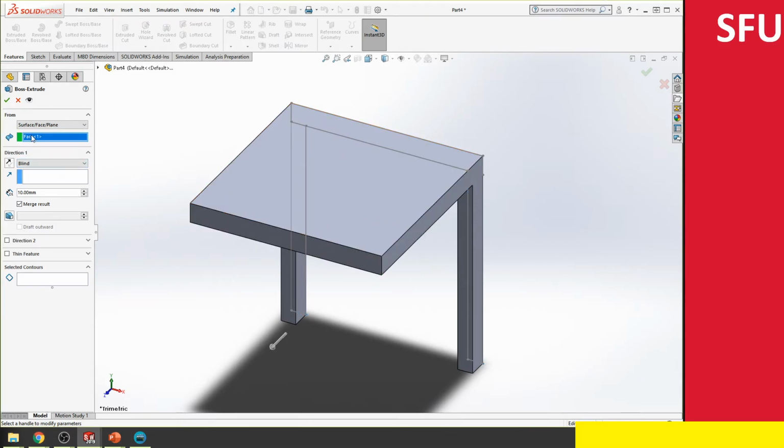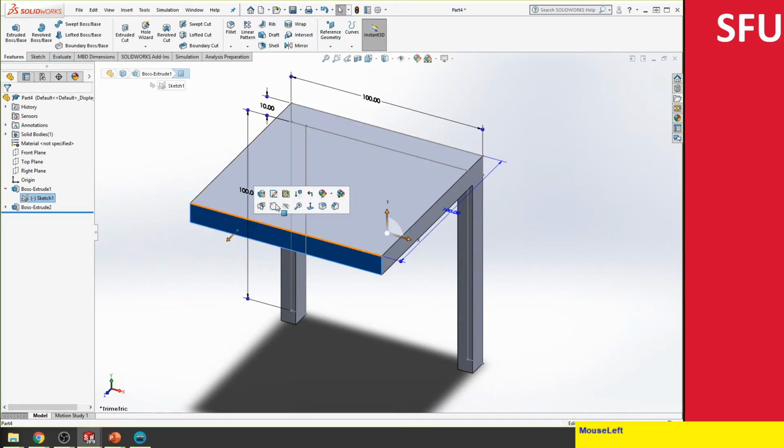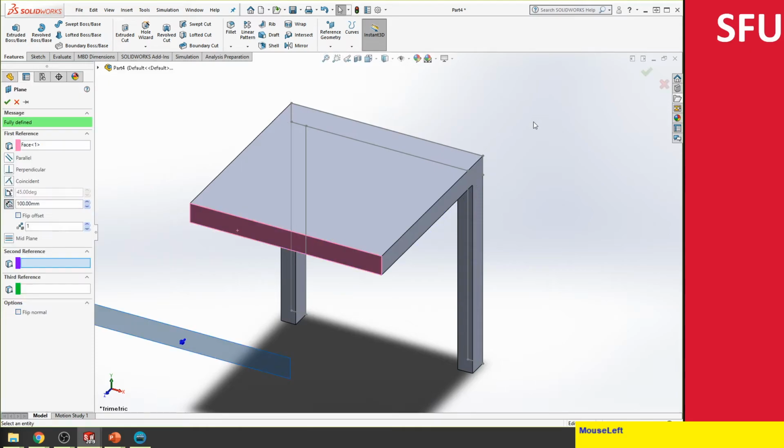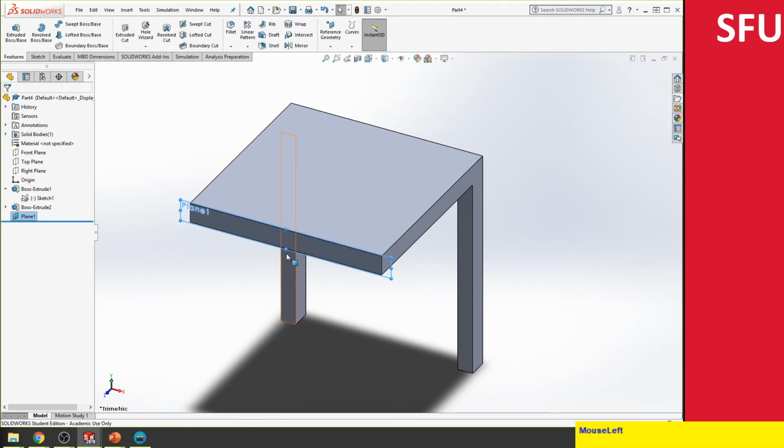If you really wanted to do that, what you can do is create another reference plane over here. So we can select here and then create a reference geometry which would be a plane, and then we can make it coincident and then say okay. The visual of the face can be changed by dragging these little limiters.